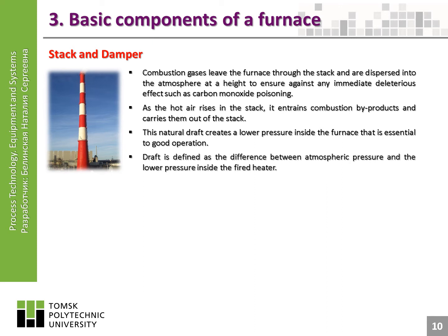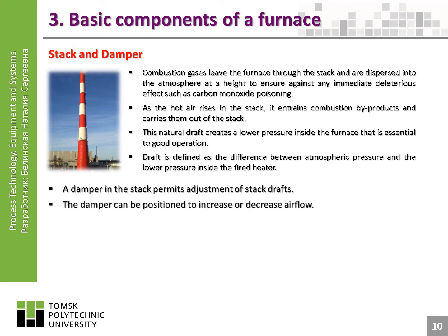Draft is defined as the difference between atmospheric pressure and the lower pressure inside the fired heater. A damper in the stack permits adjustment of stack drafts. The damper can be positioned to increase or decrease airflow.